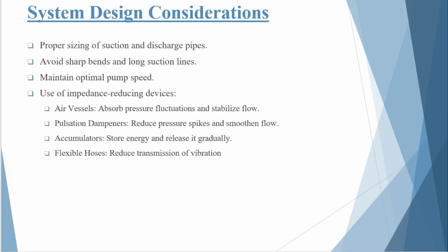Another important point is to avoid unnecessary elbows, tees, strainers, and sudden changes in pipe direction. These fittings increase friction losses and disturb the flow pattern. When friction loss combines with acceleration head, the suction pressure may fall below the liquid's vapor pressure, leading to cavitation.